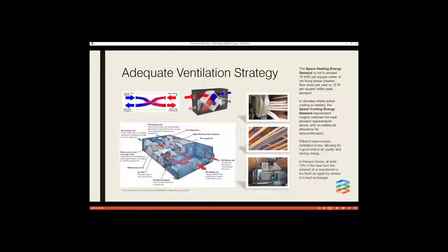Must ventilate, okay? It doesn't matter how any of those methods are actually applied, it's really important that it's done. What's on this slide here is the insides of an MVHR unit and how the air exchanges. You've got your heat and cool passing each other, so intake air passing the exhaust air, and that heat is being transferred, and the constant temperature is maintained inside of the building. The different installs, the different types of ductwork through there.